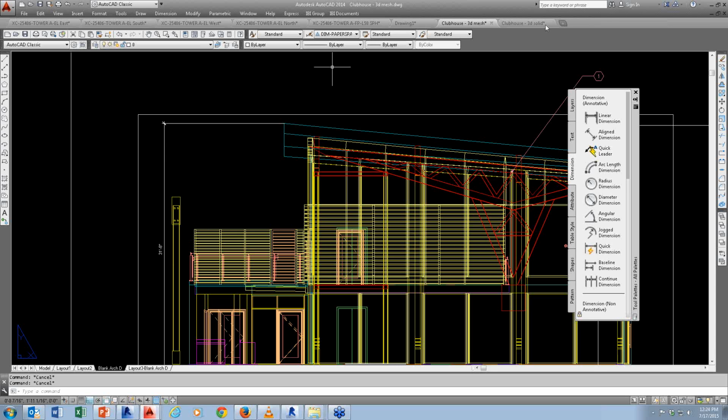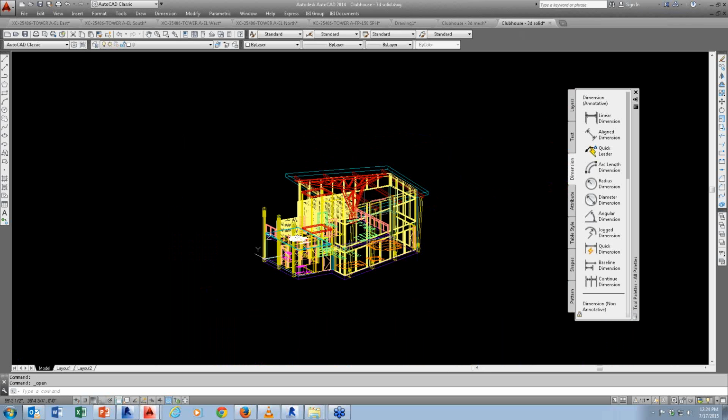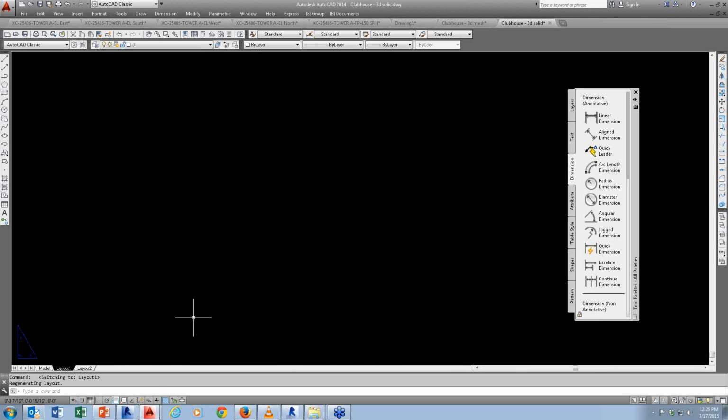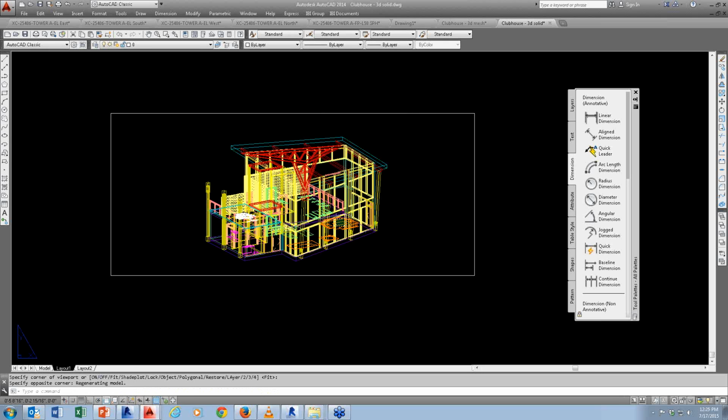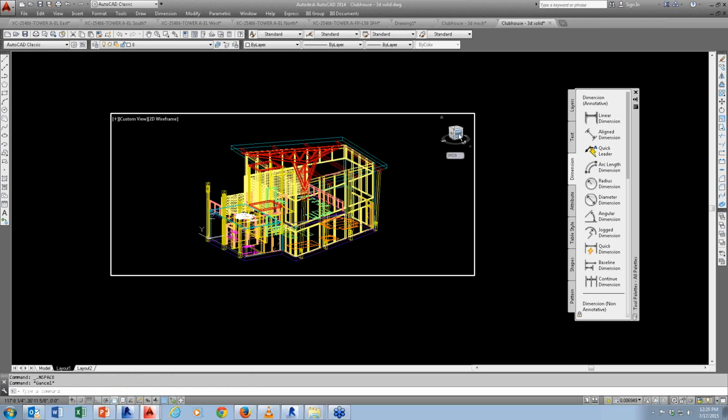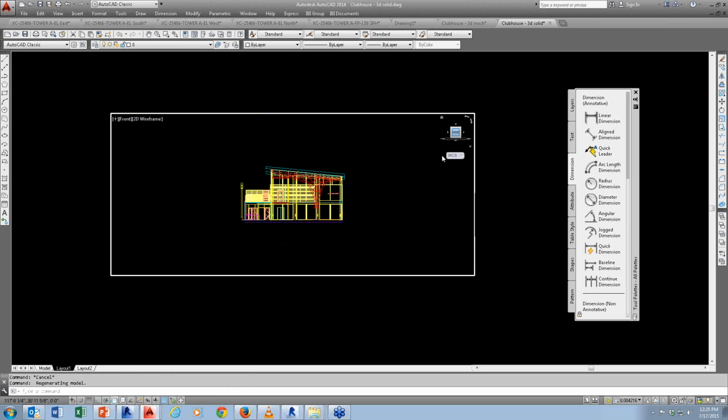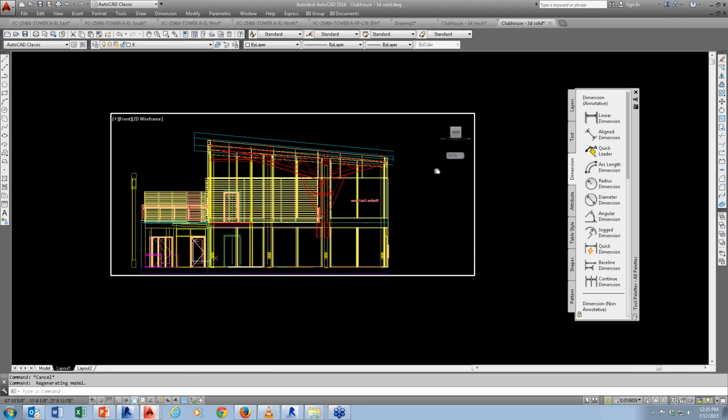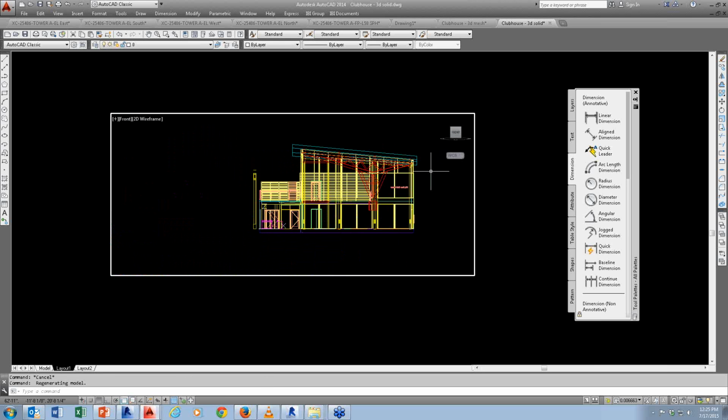Okay, let's say you get a clubhouse similar to this, but it's actually a 3D solid. What would you do? Okay, so it's the same application. All you have to do is just create a view here. I'm just going to go here, view. If you want to generate, let's say, a 2D elevation based on that, what you have to do is type in the command called solid profile. That's SOLPROF.